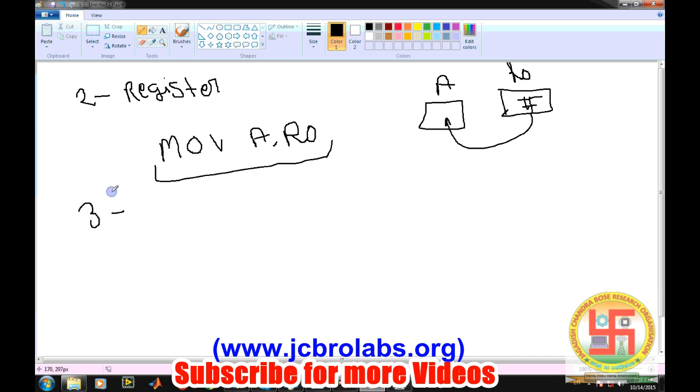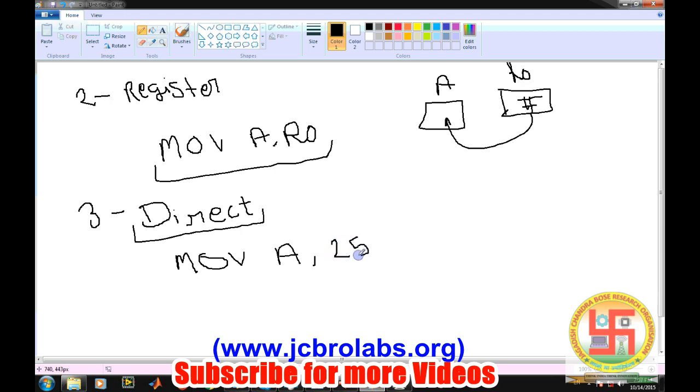The third addressing mode is the direct addressing mode. In the direct addressing mode, one of the operands is the address of a memory location. If we write MOV A, 25, taking the last example: previously we put a hash sign, and with the hash sign it becomes data, but if there is no hash sign, it becomes a memory location.